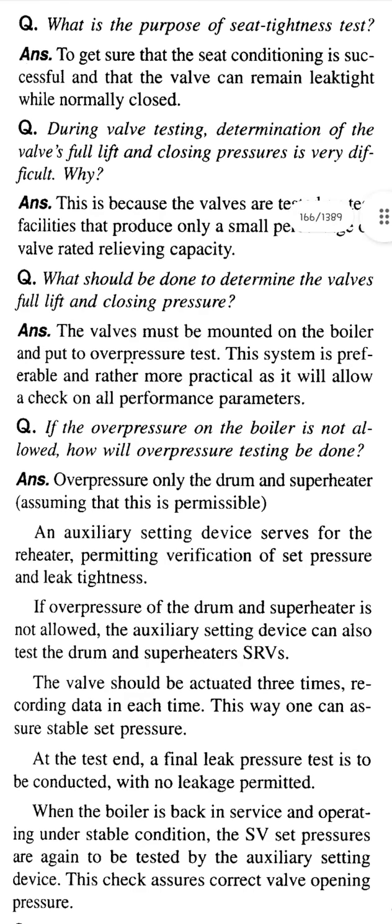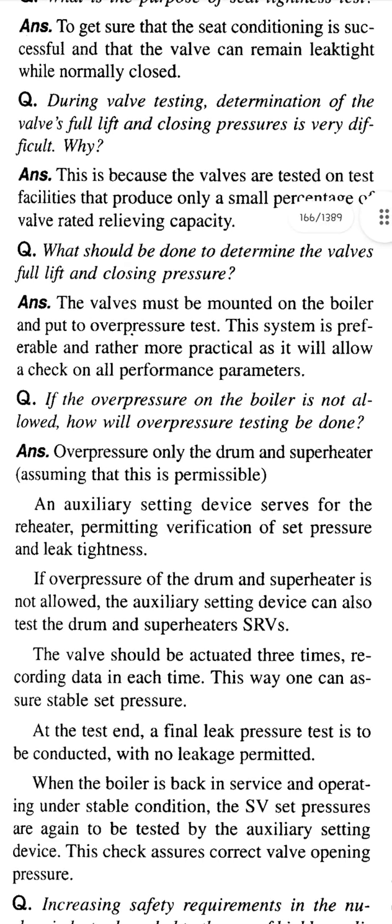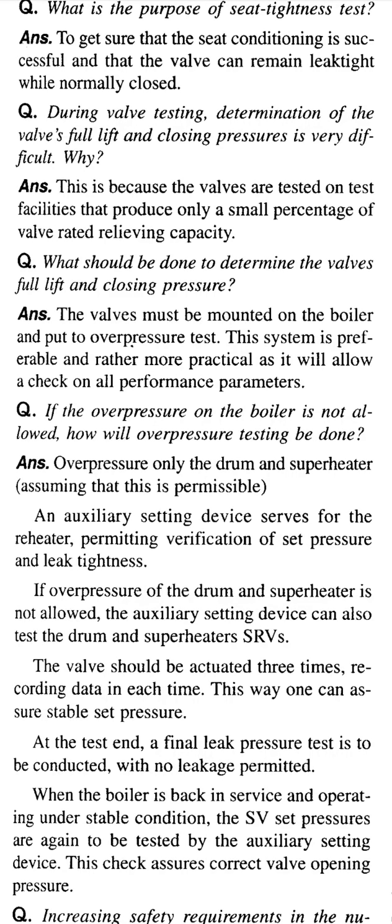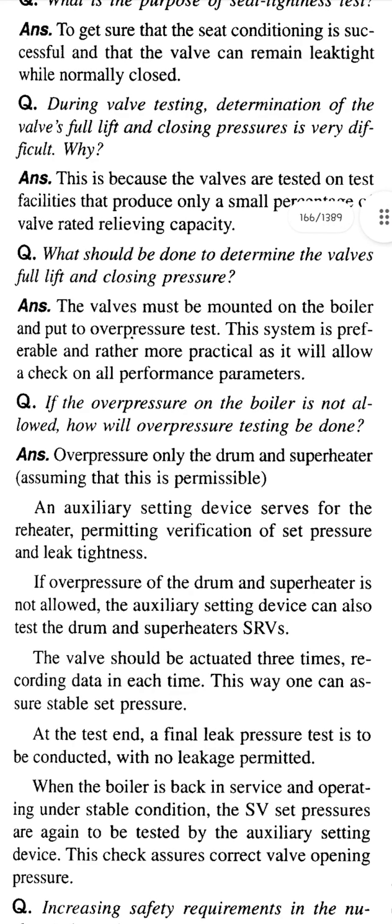Question: during valve testing, determination of the valve's full lift and closure pressure is very difficult. Why? Answer: this is because the valves are tested on test facilities that produce only a small percentage of the valve's rated relieving capacity. Question: what should be done to determine the valve's full lift and closing pressure? Answer: the valves must be mounted on the boiler and put to an overpressure test. This system is preferable and rather more practical, as it will allow a check on all performance parameters.